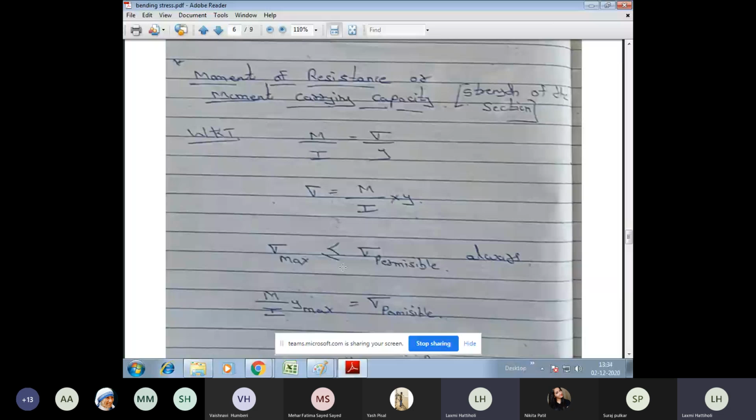While designing, whether it is a beam, column, or any structural element, you should not design it for the ultimate limit or the maximum limit. You should be on the safer side and design it for the permissible limit, which is less than your ultimate point. In my case, if I take a rectangular beam of 100 kilonewton, you should design it for around 50 or 60 kilonewton.